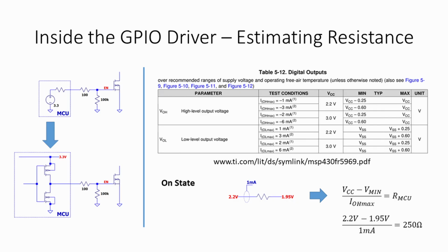So the 10K to 100K pull-down range stays an order of magnitude or two from resistances that will cause problems with turn on and turn off, and it has some margin against part and environment variation.